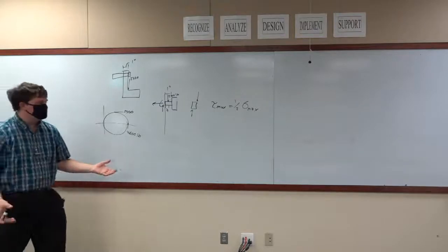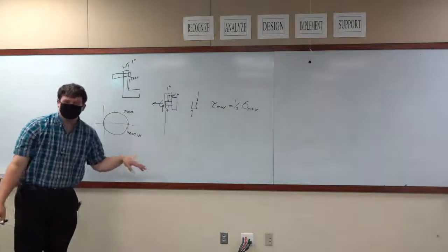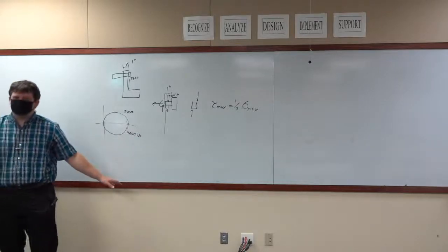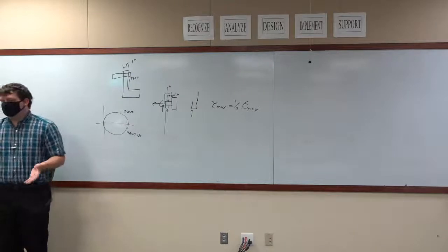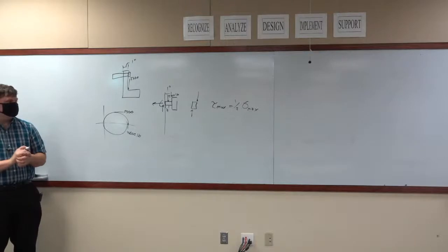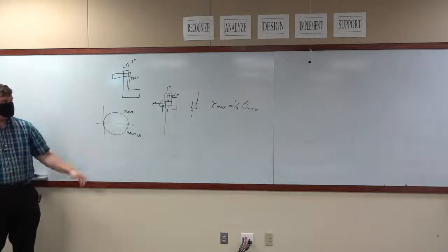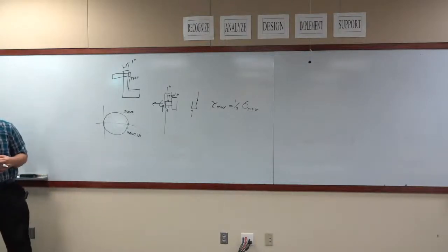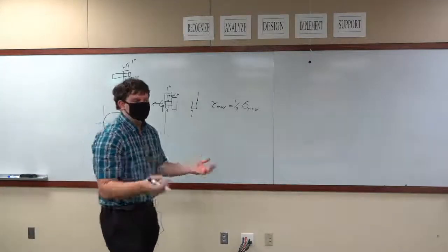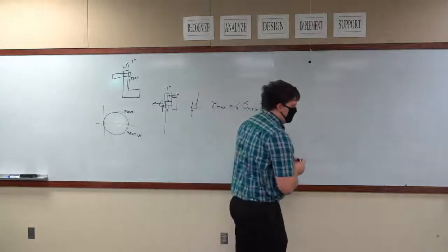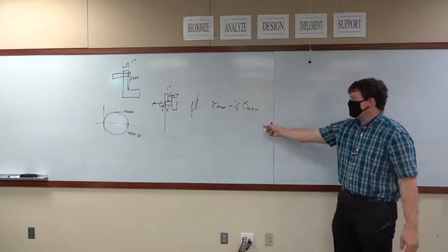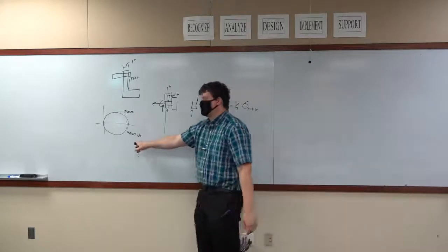So what we're dealing with here is you need to have a bolt that can handle 4,600 pounds of tensile load. If you can design a bolt that does that, you've got a bolt. That's it. Now there is a lot of other theory and considerations that we have to take when we're talking about this. We'll talk about that more when we actually get into discussing bolt design. But this is generally a problem that now I know what I'm looking for. I'm looking for a bolt that can handle 4,600 pounds.